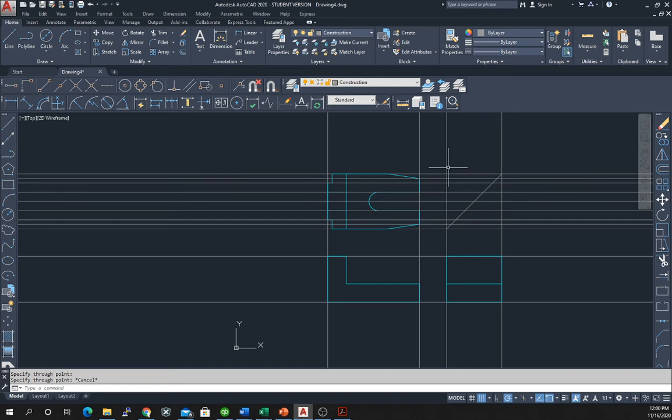Now, it turns out you could actually simply add lines instead of construction lines. It really doesn't matter because it is in the construction layer. What we're going to do next is we're going to pull these construction lines from that 45-degree miter down. So everywhere we have a construction line intersection, it's going to add a construction line going down.